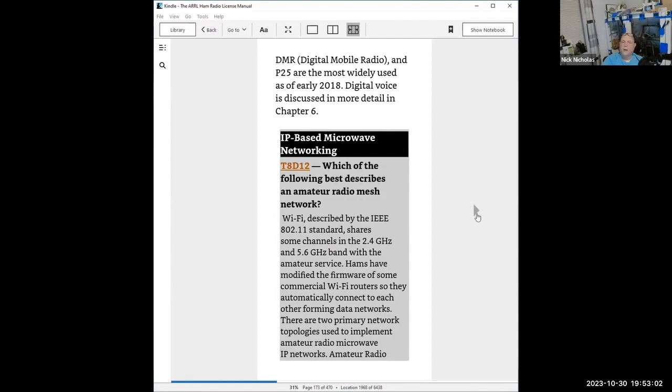The advantage of digital radio is, first, it can be compressed and you can send it in smaller bandwidths. Second, some of them, like C4FM, reproduce audio phenomenally. DMR radio is probably the lowest quality of reproduction, but it has the advantage that it more efficiently uses power in a narrower bandwidth, so it gives you a greater range. So you're going to find a great deal of digital coming up in the future. And audio, digital, and we're even beginning in the amateur world to use digitized TV. You already have digital TV if you ever Skype, and you're using digital TV right now in this class. This is how this whole trick is done. It's all the same technology, just different protocols.